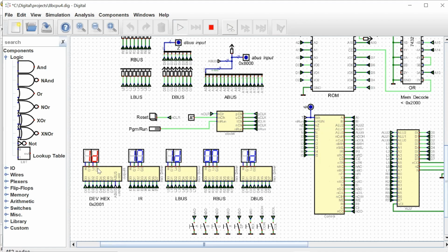So we in fact are running through all of the test cases, and I said there's about 36 of them, and this is hex. So that's up to 32, and that's it. And running through, we have no errors. And that is really important, to have that test harness. I used it a lot when I was completing the design work, and it allows me to refactor things and change things around and just run the test harness to see that we, in fact, didn't break anything.